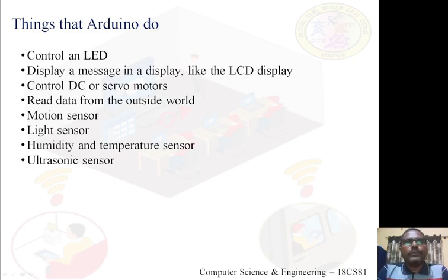One more thing, there is a special sensor, what we call motion sensors. There is a sensor available in the market now, PIR, passive infrared sensor, PIR motion sensor. If you have interfaced a motion sensor to Arduino, you can detect any movements in the surroundings of Arduino.